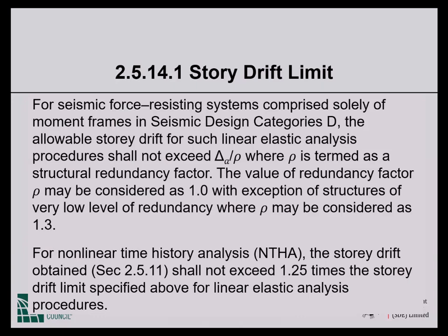Now, there is a very specific provision that I should draw your attention to. This is the BNBC 2020 section number. For seismic force resisting systems comprised solely of moment frames in seismic design category D, it should be singular category.